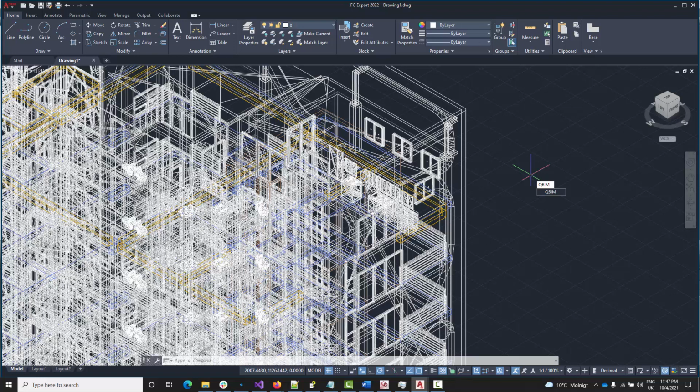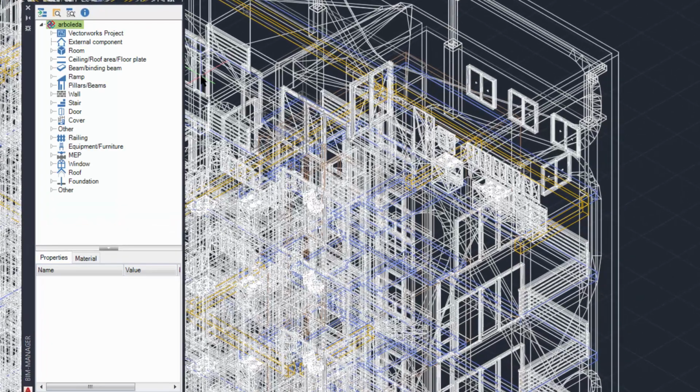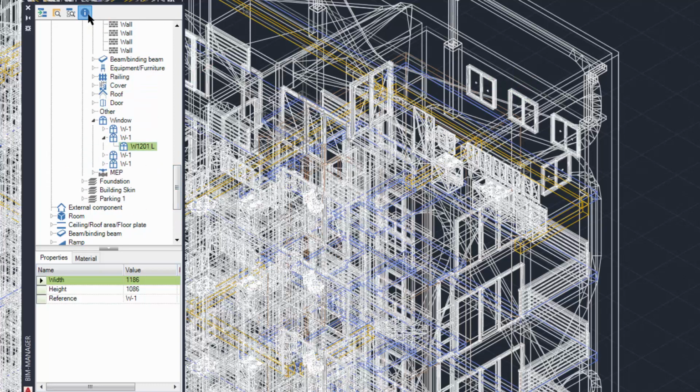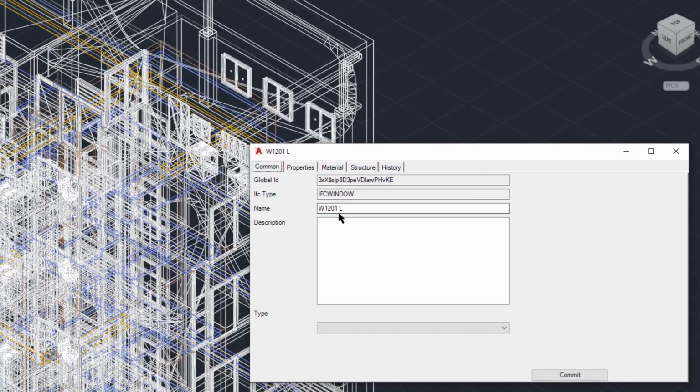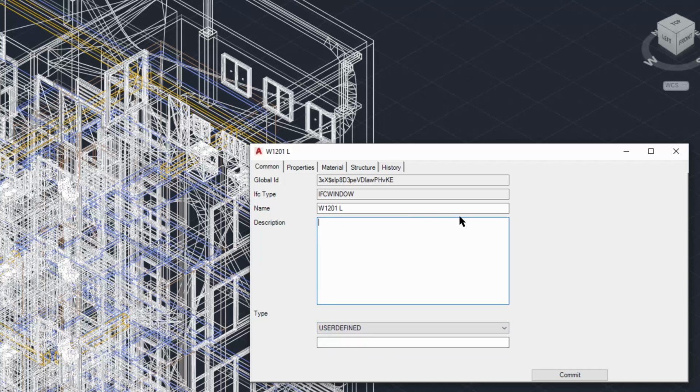We don't have a prepared sample for that scenario, but to exemplify what I'm suggesting, I can use the limited editing features of the BIM Manager. I look up an IFC object by picking one in the drawing. The picked window is located and selected in the tree structure. Using the Info button, I can access the IFC properties from the selected node. In the Common tab, I can assign some basic properties to the objects in the tree model.